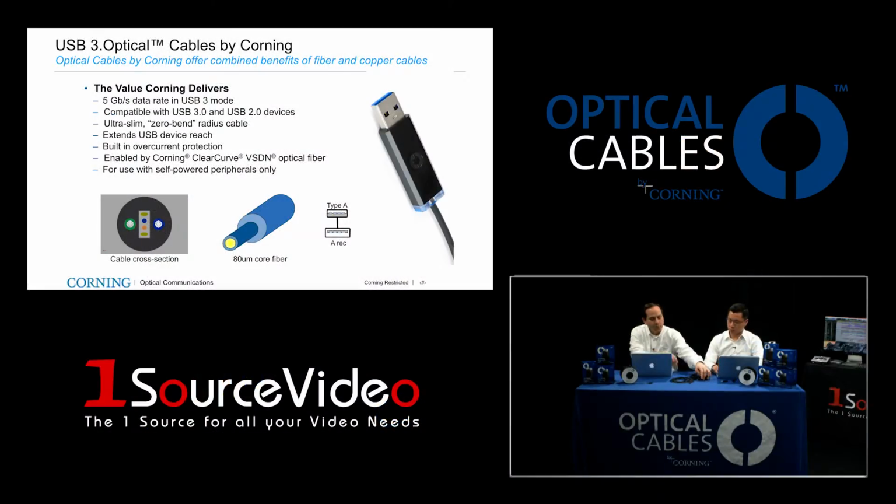What we're showing here is an extender cable. So what that means is you plug this A side into your computer and the B side will have a short copper cable that will connect to the peripheral. Again, it's enabled by ClearCurve special 80 micron fiber. And if you look at the cross section on the bottom left of the slide, you'll see we basically took the cable and cut it. There's 2 28 gauge copper conductors inside the cable.